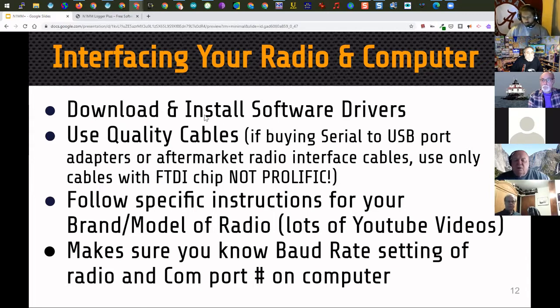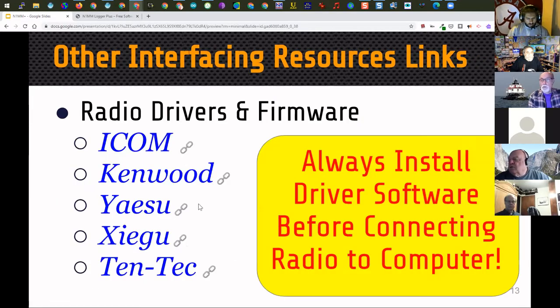I have information on interfacing your radio, and one of the things that you need to do to be able to work with N1MM is know what port your radio is on your computer. Just a couple words about interfacing if you haven't already done it, if you're planning on doing it. Always install the driver software if there's driver software to be installed before you connect your radio to your computer.